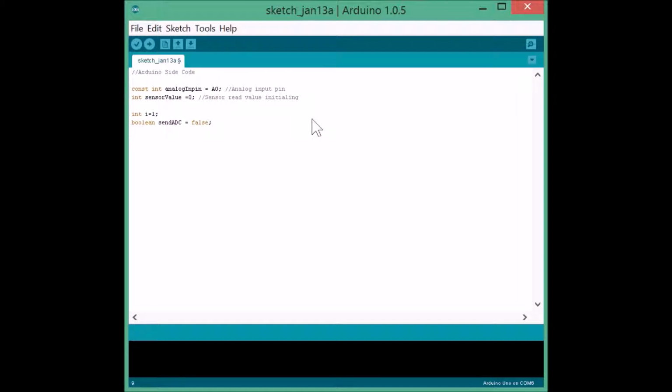As you may know, or most of you might not be knowing, the Arduino has one serial port already specified, that are pin 0 and pin 1 that are assigned to RX and TX, right? But we won't be using them, as they're used for programming the Arduino and also receiving the serial data from the serial console. So I'll be using a library called SoftwareSerial that's included in the Arduino package. So we'll just import it.